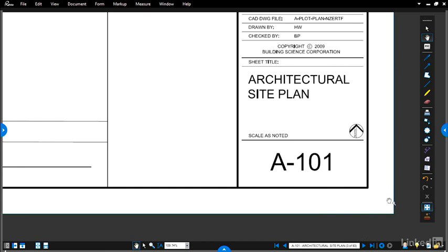So when we're talking to people about which drawing sheet we want them to look at, we want to use this sheet number, A101, as opposed to saying page 3, because somebody out in the field might have just been given 2 sheets of drawings because that's all they need, and we need to make sure we're talking about the correct sheet. If we look at A101, you see that A is also an indication that this is part of the architectural set of drawings.